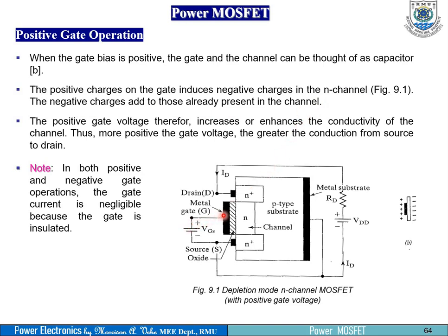So we put positive here. Any positive close to this area, because the substrate is a lightly doped p-type, so it has positive charges in it, we already know that like charges repel. So the positive potential will push away anything that is positive from this region and seek to attract anything that is negative, because unlike charges attract. That is why we are saying it will induce. Maybe I can go to my pointer option and underline the word induce, or induces. So that is happening over there.